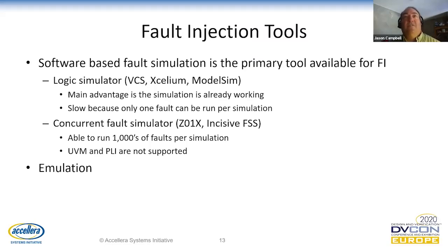Also, emulation can be used. Emulation is expensive, and it actually suffers from both the limitations of the logic simulator and the concurrent fault simulator. So it's not a great tool for fault injection. But if you want to simulate a long-running application, such as booting your application and running something, emulation is often the only thing you can use. A software fault simulator just won't run fast enough.